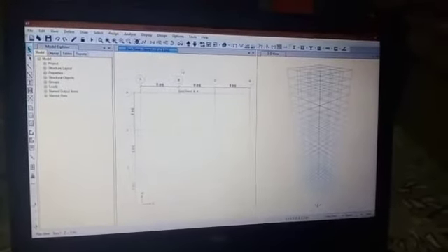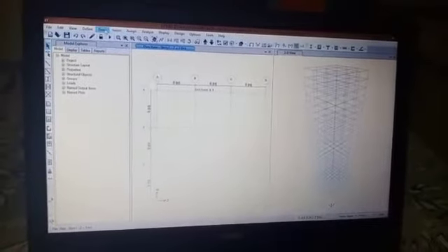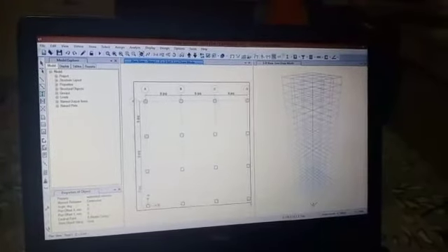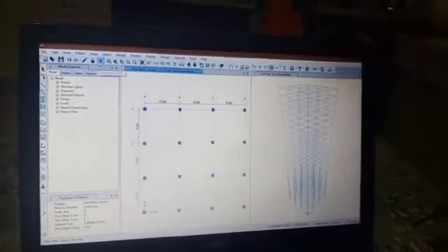Now we have to draw all the elements in their specific positions. Make sure that the similar stories option is selected and then choose quick draw column from the draw menu, draw beam or column of base objects and quick draw columns, and then make sure that the property selected is auto select column which you have created, and now draw all the columns. Now click escape.